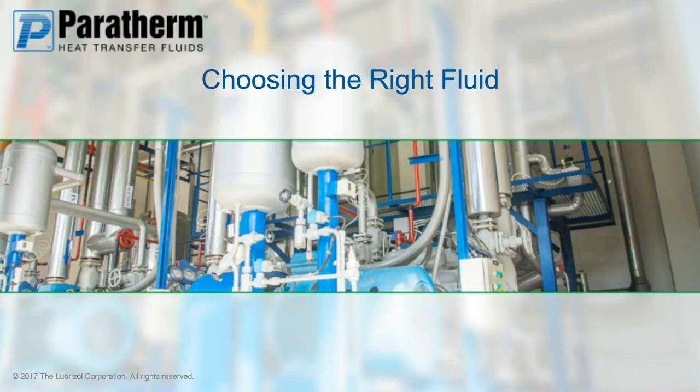So very important, I know we're talking about fluid flow, and you would think that would be a mechanical issue or what you have in your system settings or your pipe size or something hardware. But truthfully, the first and most important element that you can control when talking about fluid flow is making sure you actually have the correct fluid for your application. Now, this is crucial. One of the things that affects fluid flow the most is going to be the viscosity of the fluid itself.